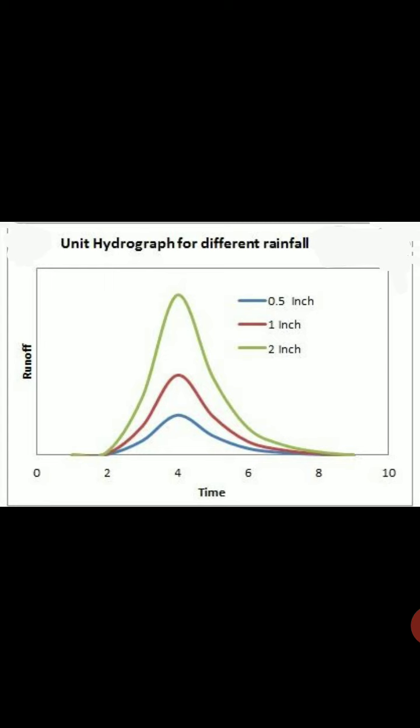First point: select a hydrograph resulting from an isolated, intense, short duration rainfall of nearly uniform distribution over the entire drainage basin as well as within its duration.